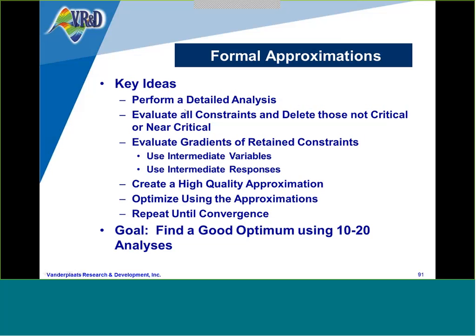So the key idea is we do a detailed analysis, evaluate constraints and delete those that are not critical or near critical, get the gradients of what's left, create a high quality approximation, use that to optimize, and repeat that. That's one cycle in the process.